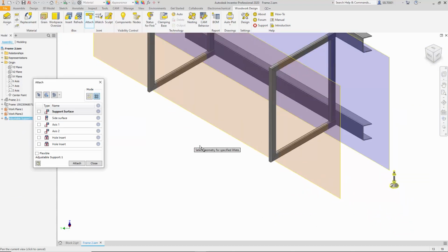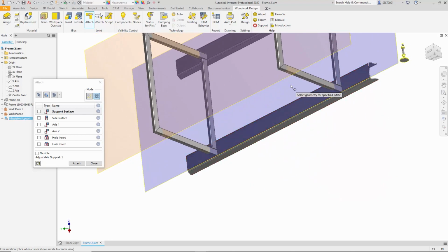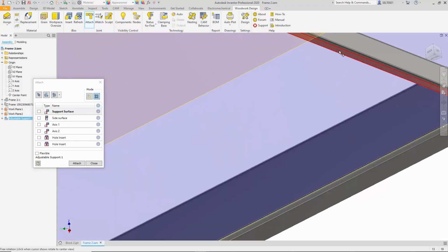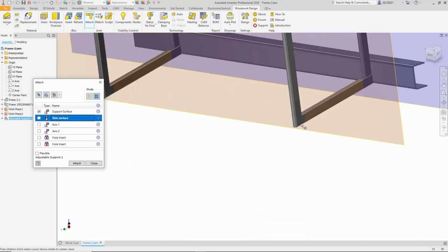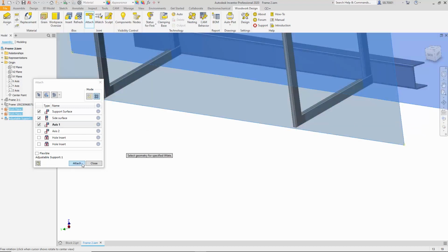However, if we want to change the position of the legs and put a distance of say 120 mm, we can see that the required holes are not cut for this element. Therefore, we use the features of woodwork for Inventor and indicate where we want the holes to be cut.